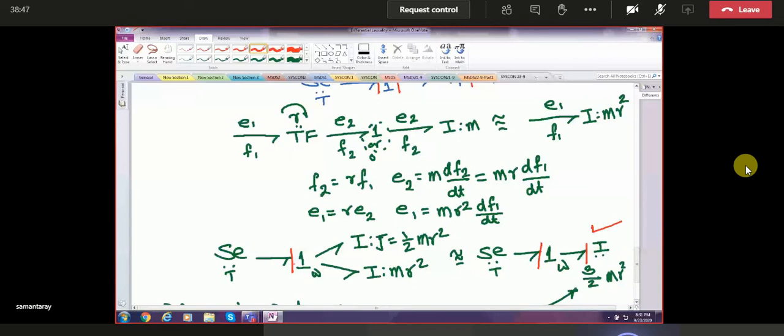Likewise, in the previous case, you can get an almost ideal voltage source charging the capacitor in zero time by setting the value of R very small, but not zero. Then it will be equivalent to the cell directly connected to the capacitor. So these are singularities. These singularities arise because of differential causality. We need to remove them.